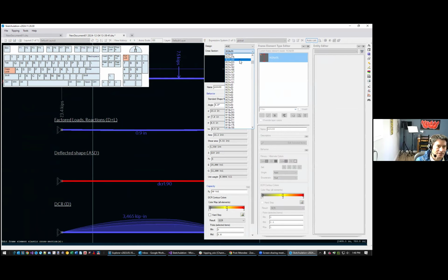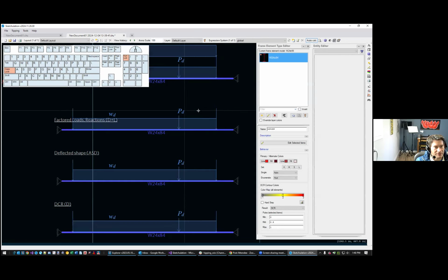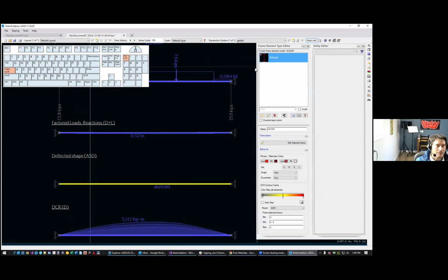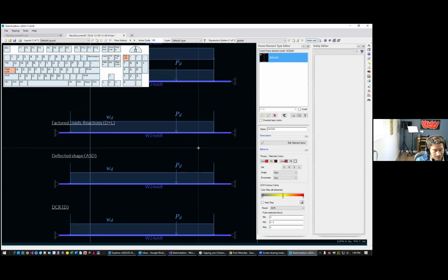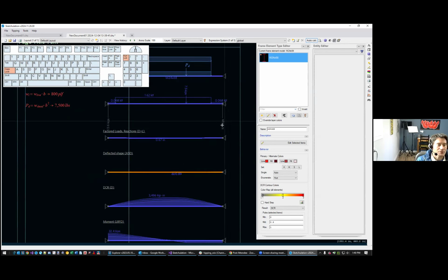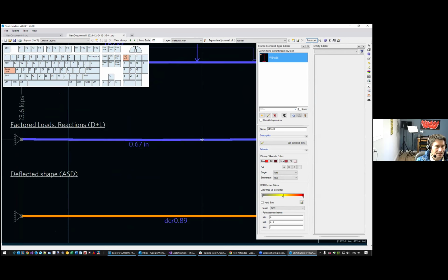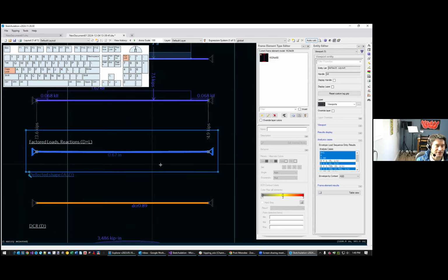I'm going to stick with the W24, but maybe, let's see. I think I'm going to have a hard time with the W24 actually. Oh, that worked. 24 by 84 worked. Pull this down. Let's go 24 by 68. There we go. 24 by 68 is working under dead load, so I'm good to go. And I can see my deflected shape here is 0.67 inches.